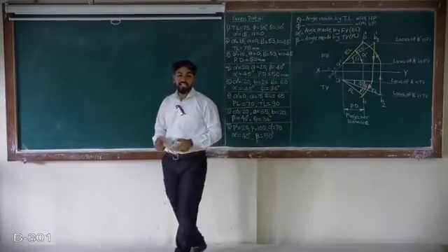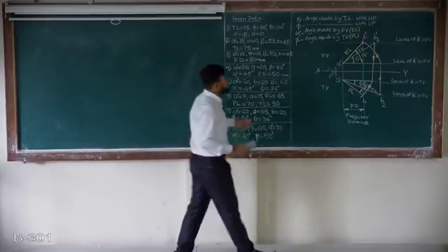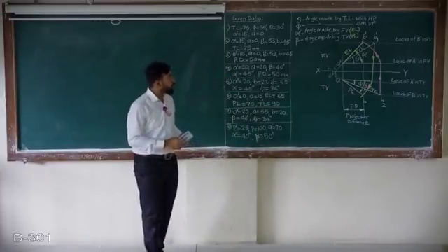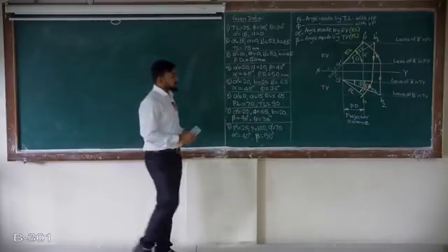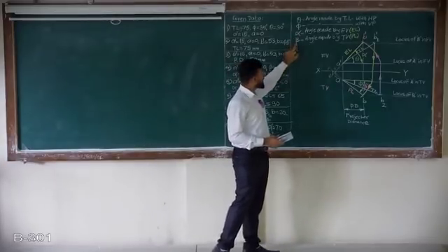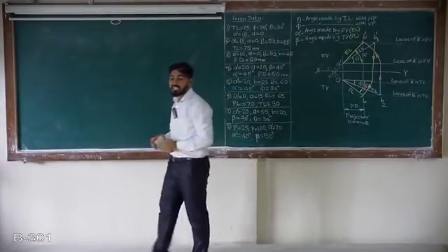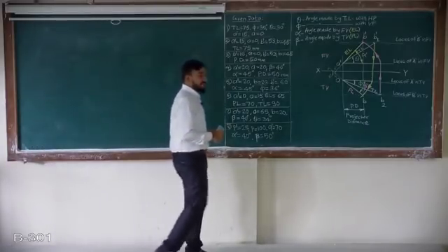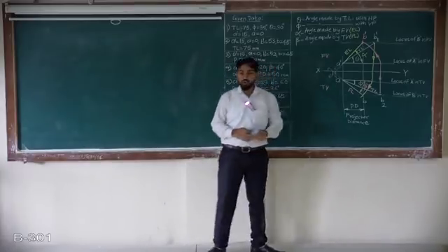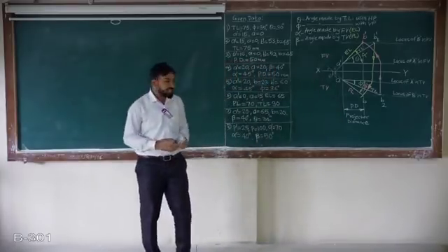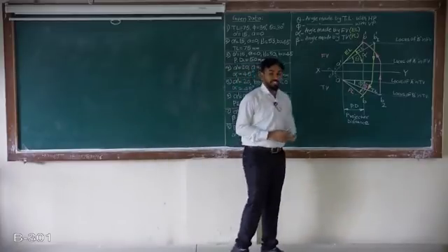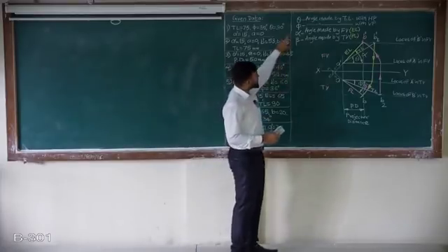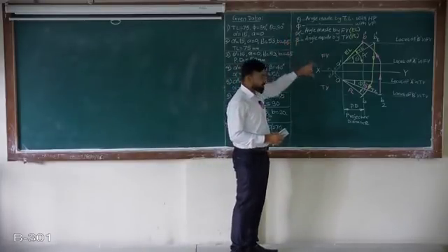So what is theta? Theta is the angle made by true length of line with HP, whereas phi is the angle made by again true length of line with VP. Next, apparent angles, they are alpha and beta. Alpha is the angle made by front view or elevation length. Beta is the angle made by top view or the plan length. So always finding out the correct given data from the problem is very important. That's why first we are focusing on the nomenclature, or you can say the parameters of oblique lines.